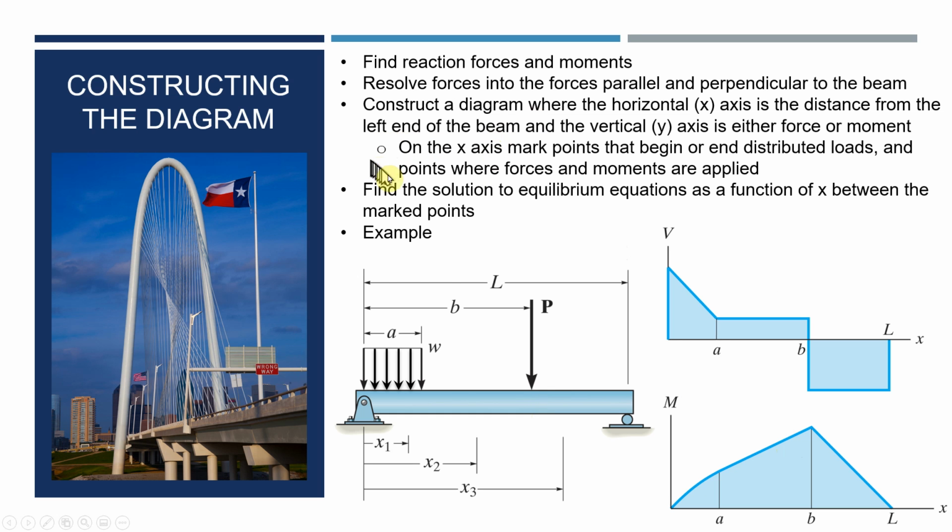So this section right here is dividing up the beam into the three sections. That we have to consider this first, and the distributed load stops here. So this will have a new free body diagram, this section here, and this will have a third free body diagram because you're transitioning force all of a sudden.